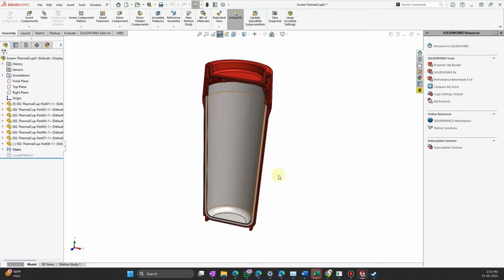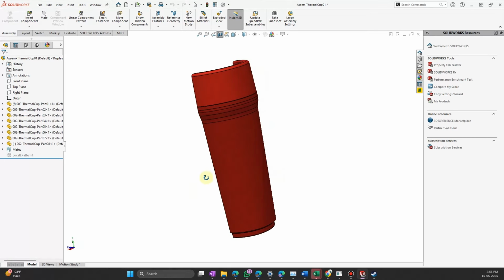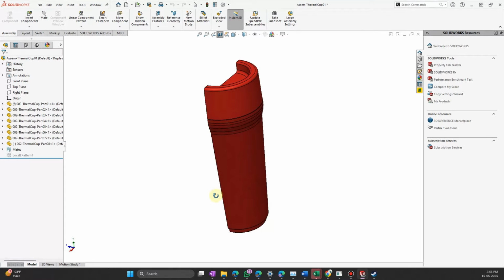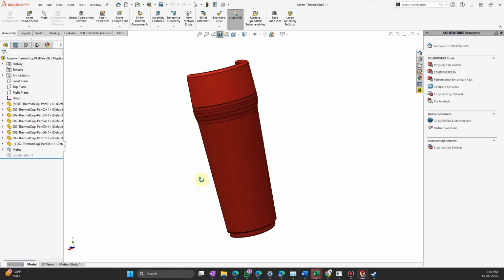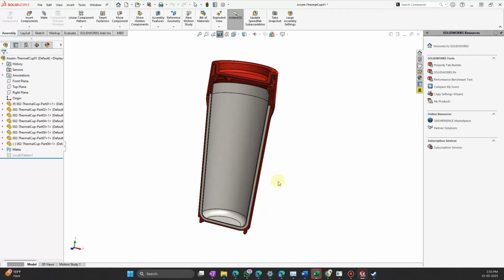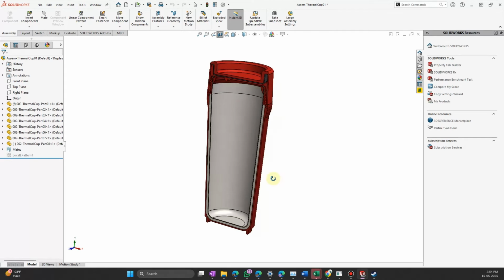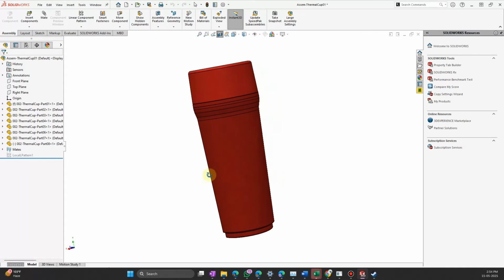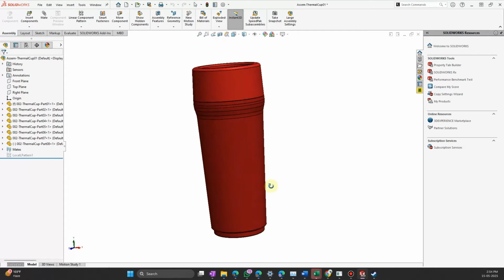So the surface A should be neat and clean, have desired surface finishes, and surface B isn't really a concern. So surface B can have the ejection pin marks, gate marks, ribs, mounting bases, and other design features and surface imperfections, since they're not going to be seen by the users. However, as I said, the surface A needs to look neat and clean with the desired surface finish.